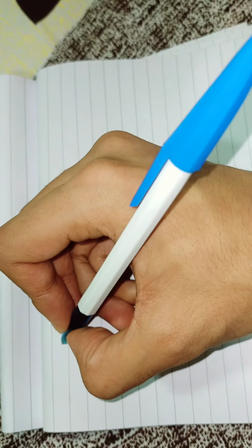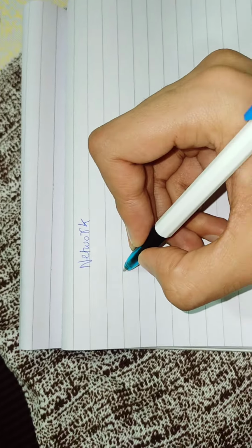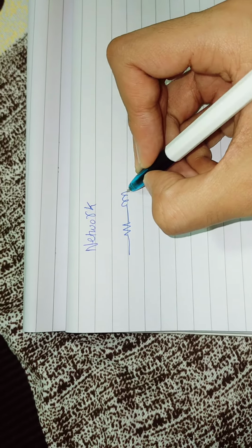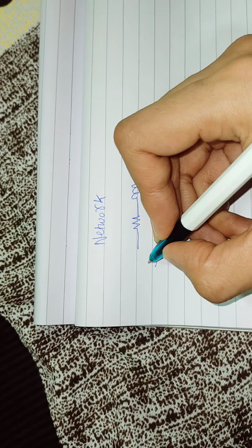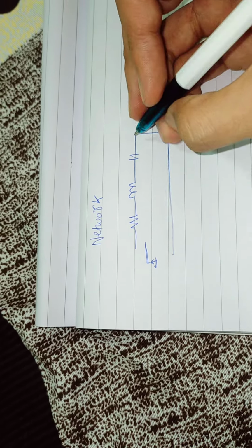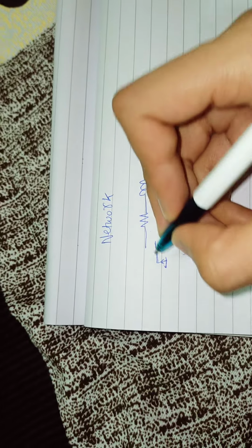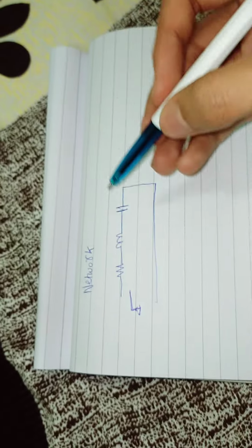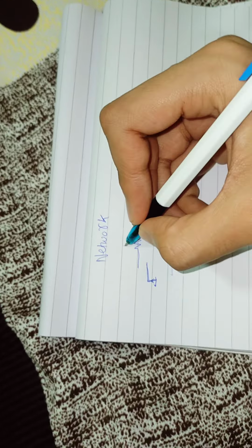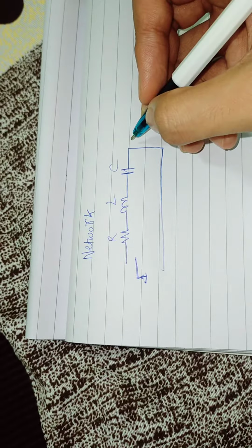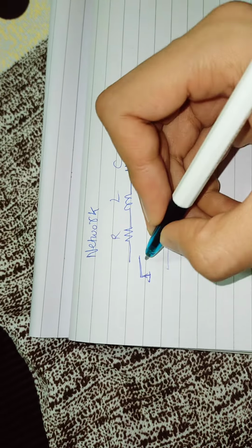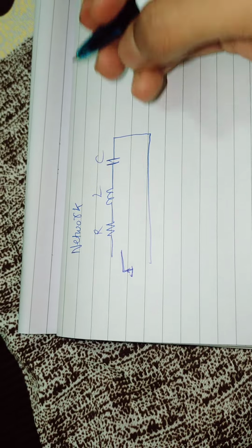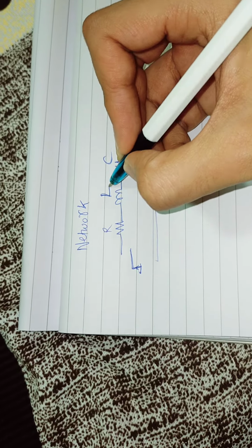And there were some questions from network theory as well. They gave me an RLC circuit, and they told me that a step input is provided here, and they asked me to explain the working without writing any mathematical equation. How will this R, L, and C behave when this step is applied to it? It's simple if you know control system basics: the response could be underdamped, overdamped, or critically damped. So it all depends on these RLC values that we are applying.